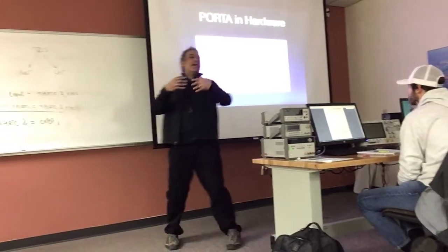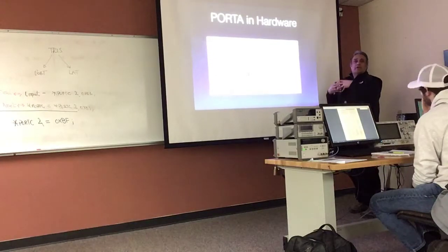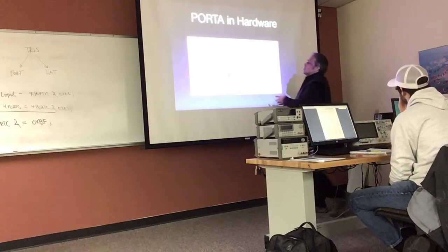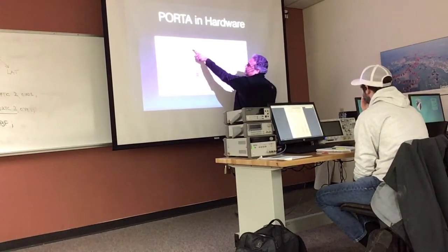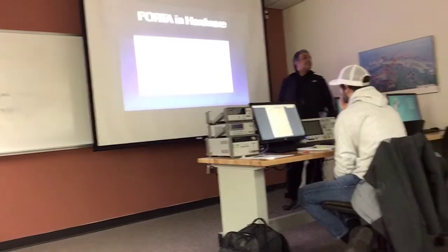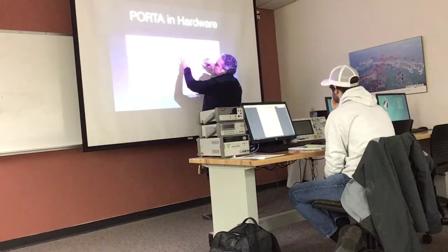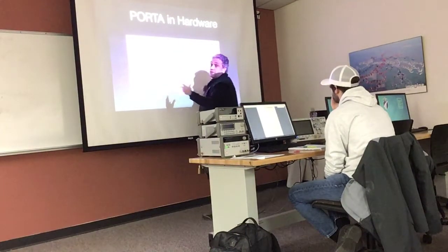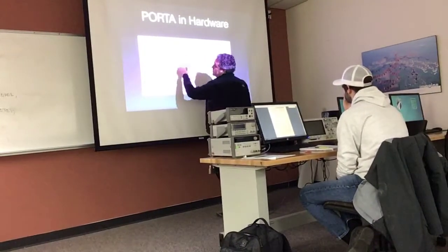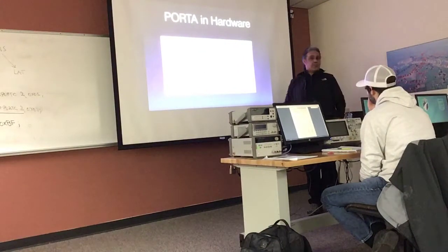But I want you to notice that multiplexed in the same physical pin, there are more hidden behaviors. And every behavior is a circuit, by the way. So you have a digital circuit and an analog circuit in the same pin. See that? It turns out that by default, you could make this processor come up all digital or all analog. When you buy the system, most of these pins, all of these pins, will actually naturally boot up as an analog pin.